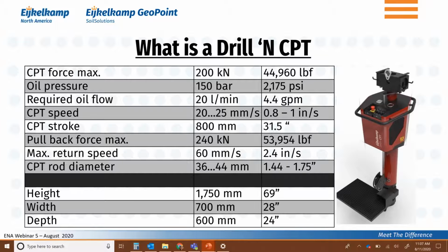And normally when you go down 60 feet or so, you have 20 interruptions where you have to move the clamp up and down. And now you'll have about 24, 25 interruptions. So it will take you slightly longer, but nothing is really affecting your CPT data.